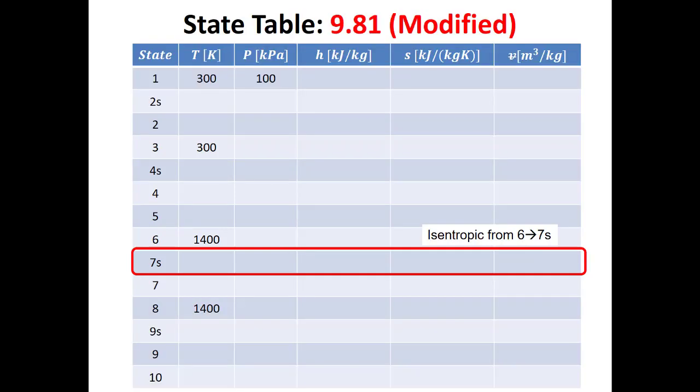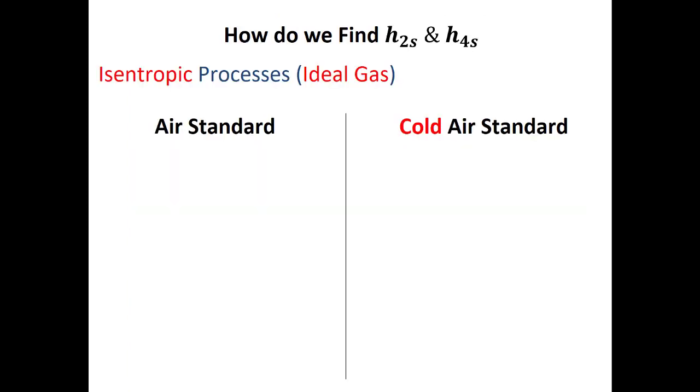So my next isentropic process, right? If I get lost on one of these cycles that uses ideal gas, look for the next isentropic process. So that's what I do here as I move through my first turbine. This is similar to moving through the compressors, where we'll have a variable specific heat analysis where we're trying to find delta H, but we don't know H7S, so we can use the ratio of pressures is equal to the ratio of the reduced pressures.